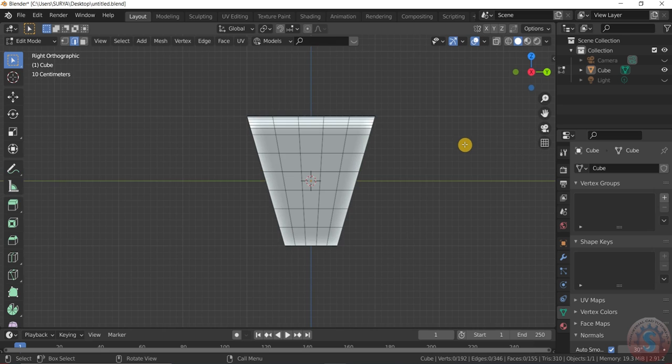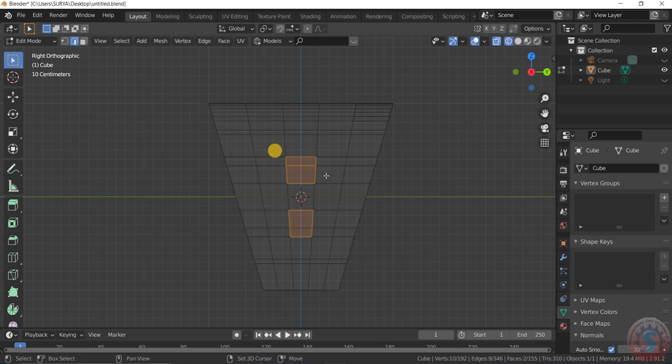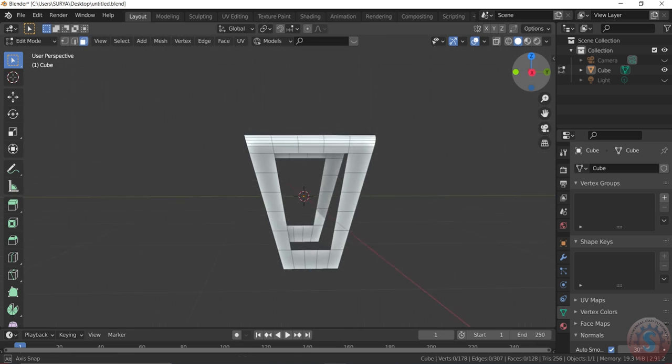Then after, I want to insert the faces, and I'm deleting the faces here. You can observe by selecting the top side view and selecting all of the faces with the face select. You can select by switching the wireframe mode onto the solid like this. In the wireframe you can delete both at a time. I'm selecting all the faces by holding the shift key and delete all of the faces, and by pressing X I delete the faces here also. See, the two holes are there.